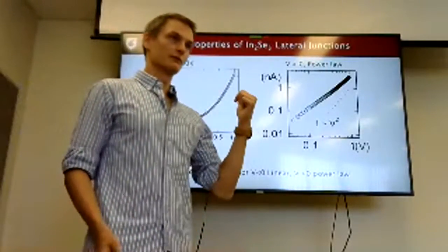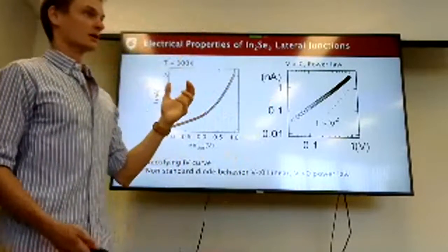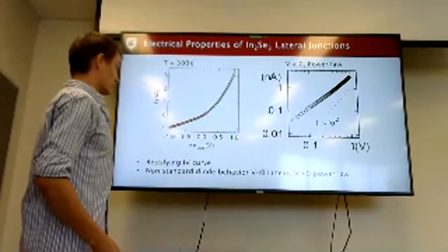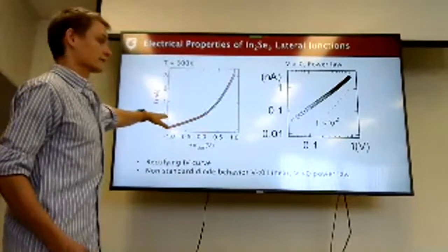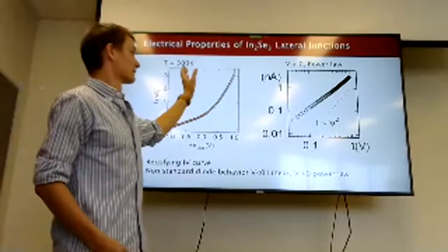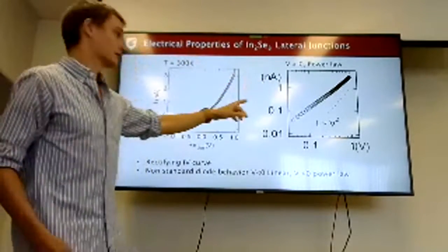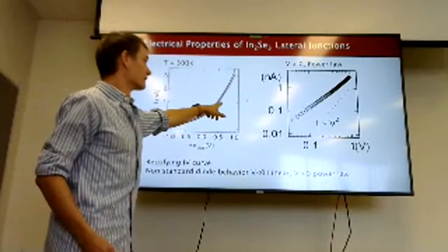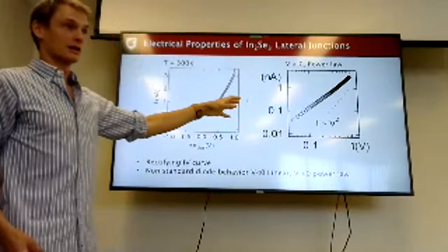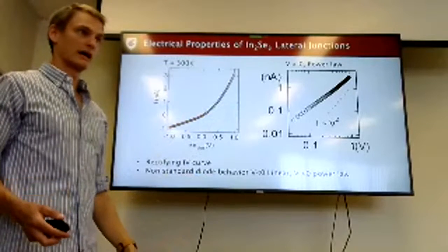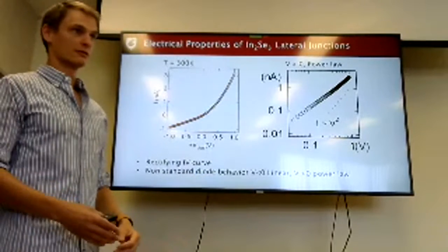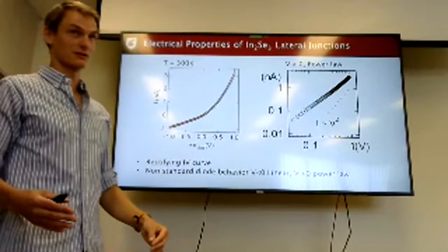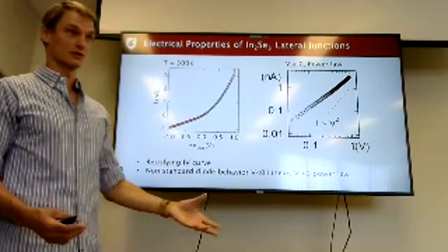And this is where we get weird. Okay, so a regular diode will pass almost no current when it's negatively biased and pass a lot of current when it's positively biased, and there's a turn on point about 0.7 volts. Which is not what we see here. The first time we did this, we thought, okay, bad device. So make a bunch more. And when we didn't get a different answer, we say either they're all bad devices or there's something interesting here.